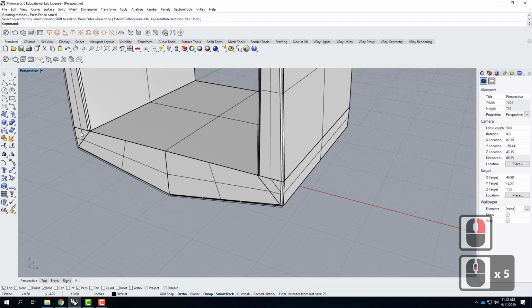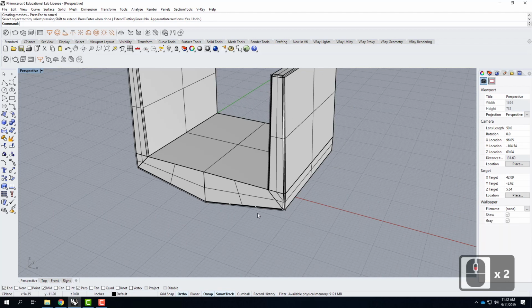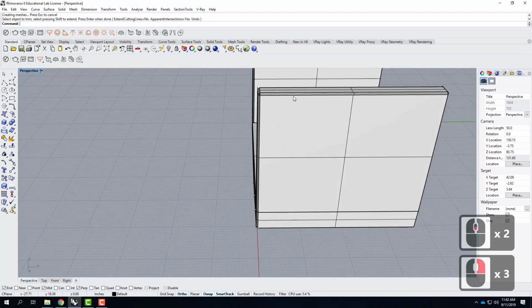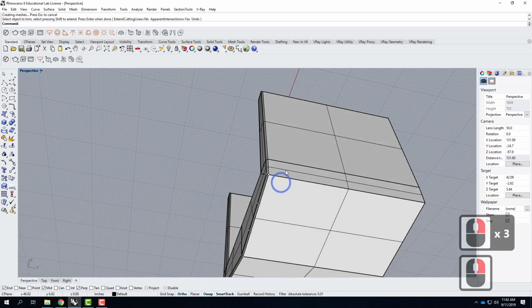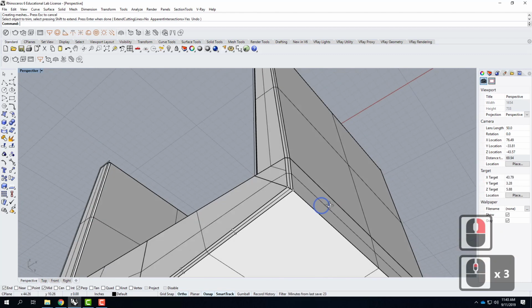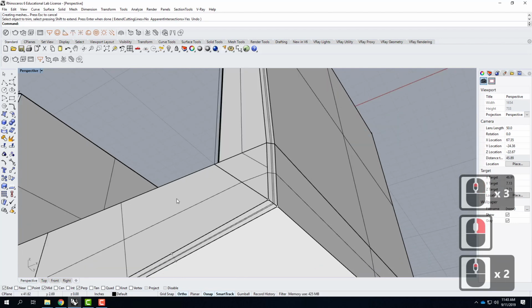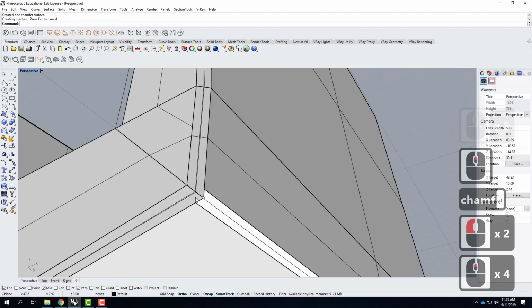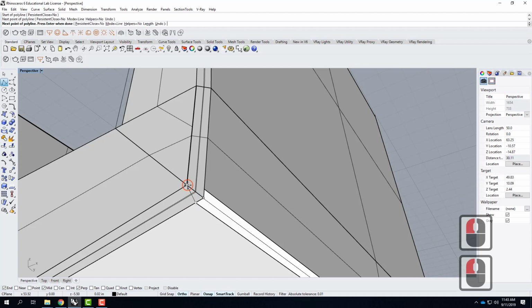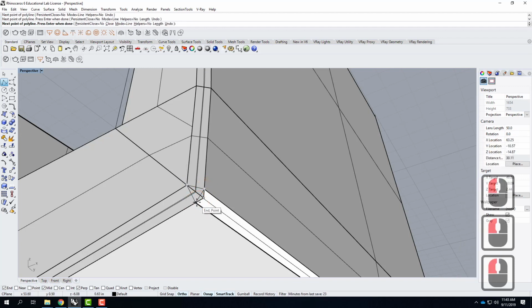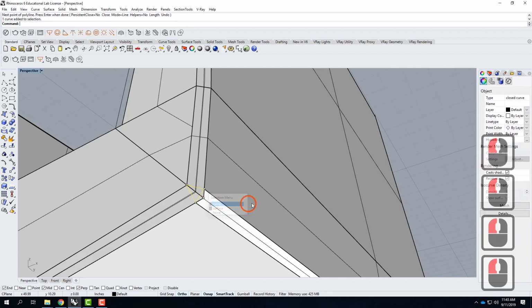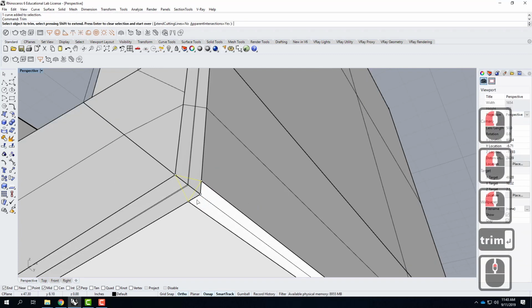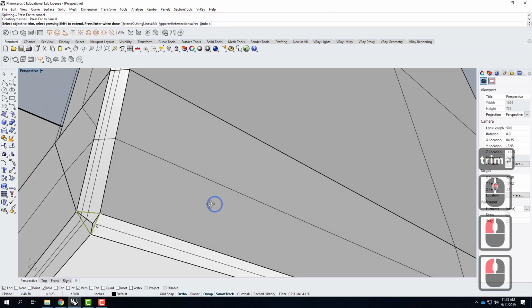So you don't have to chamfer this line right here, but you should chamfer all the way up, over, and around. Likewise, these should always be chamfered. You don't have to chamfer this outside edge, though you can if you want. If you did, there and there, you'd end up with that same triangle that you did up on top. So we'd go through and we connect from here to there, and back to there. Use that triangle as a trim for these objects there and there.